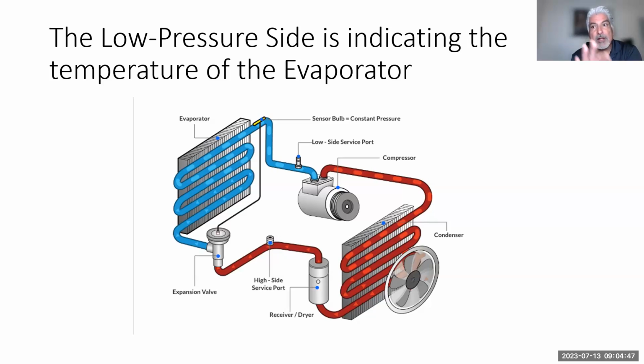For example, we got this guy years ago who wanted his van to blow really cold. What was the one thing that we did replace? That was the condenser. We're wanting to get rid of that heat from that refrigerant and have it get colder and provide better cold temperatures. So in this case, we're trying to get rid of heat. As much as the evaporator is absorbing the heat and giving you cold, the condenser is giving away the heat. So therefore, again, airflow is very critical.